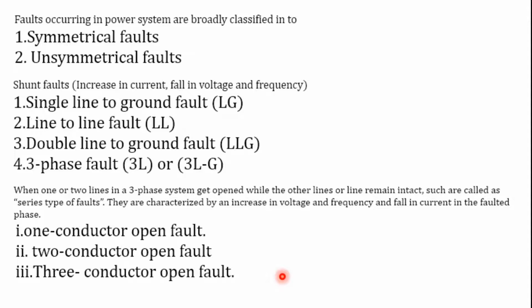The fault current will not remain the same, so the system is said to be rendered unbalanced. It involves phases of different magnitude and phase angle for each phase. Analysis of this unbalanced condition can be carried out on a three-phase basis, but this is a very cumbersome process. So there is a simpler approach: the method of symmetrical components and symmetrical networks for determining the voltage and current in all parts of the system after the occurrence of the fault.